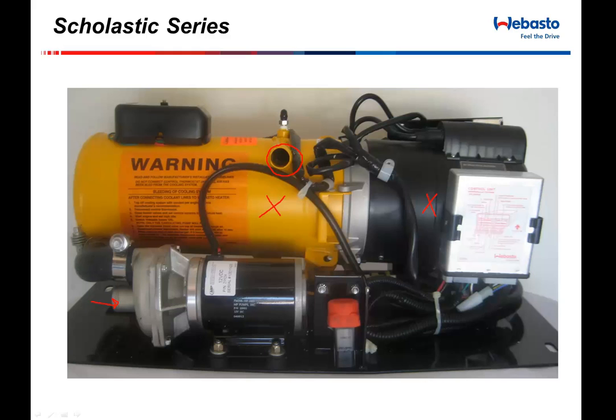Once we hit 175 degrees, the flame is turned off, but the fan motor continues to run for approximately 2 minutes. It's very important that that portion happens, and we'll go through why in a minute. That fan motor continues to operate, pushing air through the middle of that heat exchanger, trying to cool itself down.